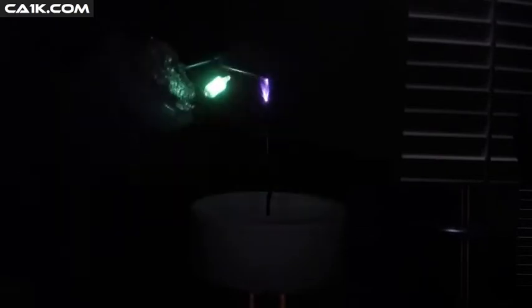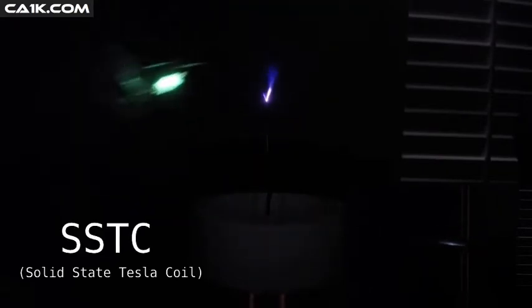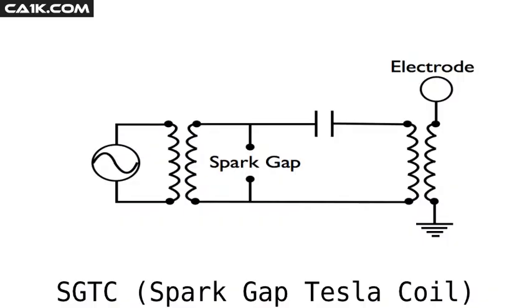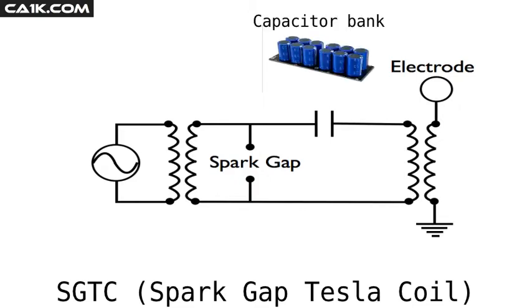In this case, the one being shown is the solid-state Tesla coil, where a spark gap is not needed to create an oscillation. But this is beside the point. We're going to be focused primarily on spark gap Tesla coils instead. Early Tesla coils needed a capacitor bank of some sort to provide the charge to activate the spark gap.